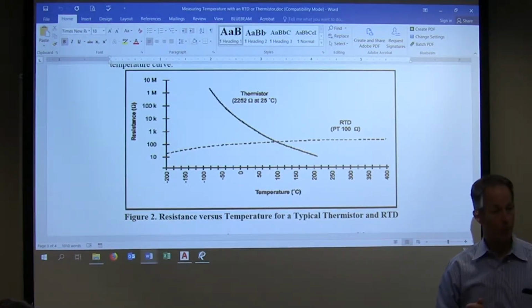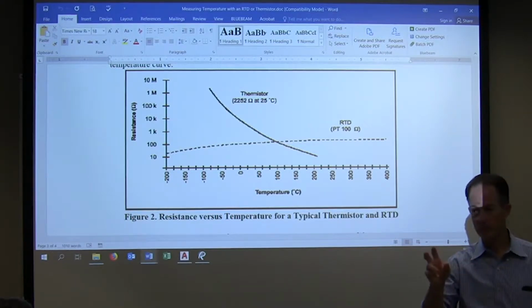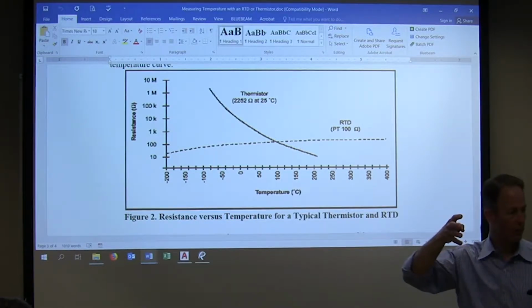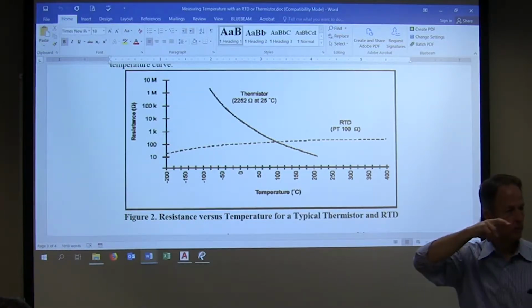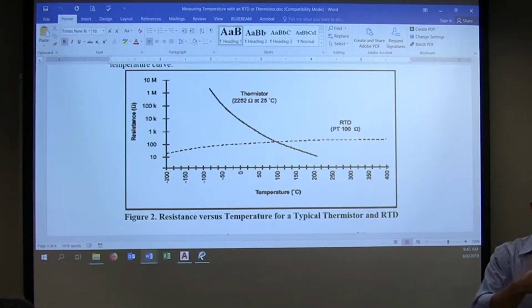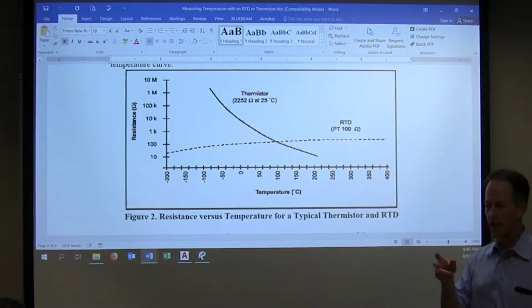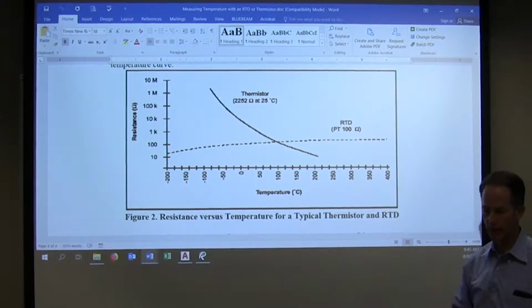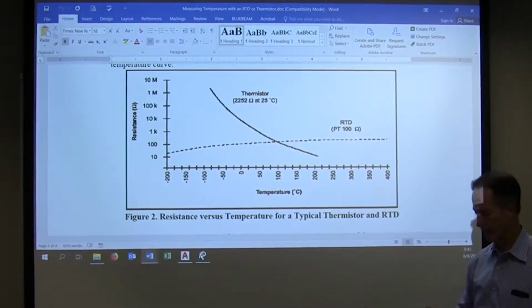Yeah, so you get paired ones, and they're put into a system together. So there's two of them in the same sensor. I believe is how they showed it. Was it four or just two? We have dual RTDs, and sometimes there'll be two. So they're dual element, and they're funky to look at how they're wired, but they kind of work, and that way you're more accurate.